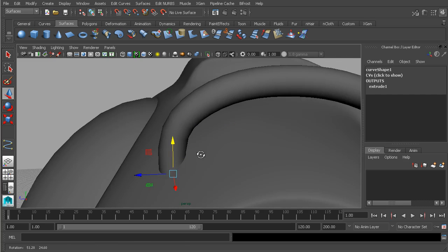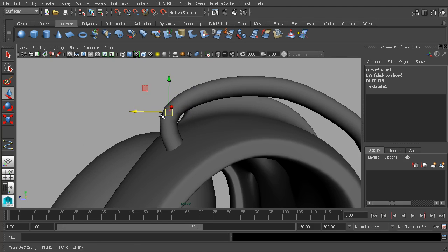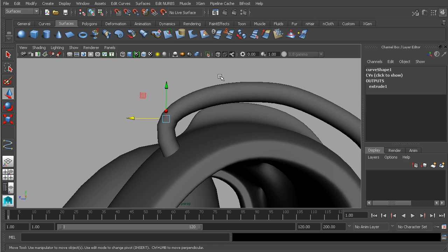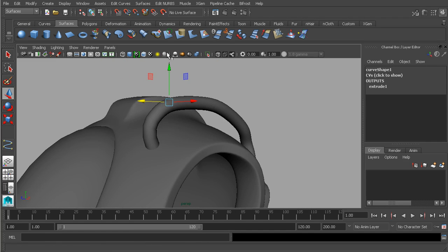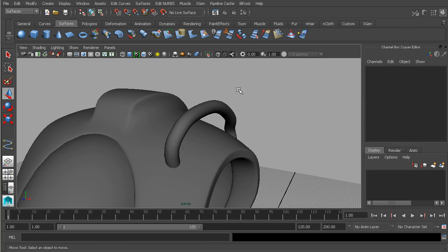I'll right click, control vertex, and I can drag across here, and I'm just going to pull this down in a little bit more so that we do have that penetration, and I want it to come in again at more of a right angle. And so I'll just modify this, and you can see the history works that way too. I can modify that path curve and the geometry updates.